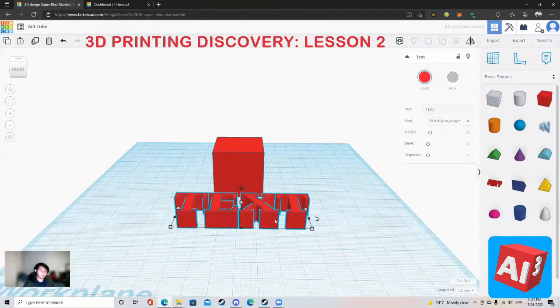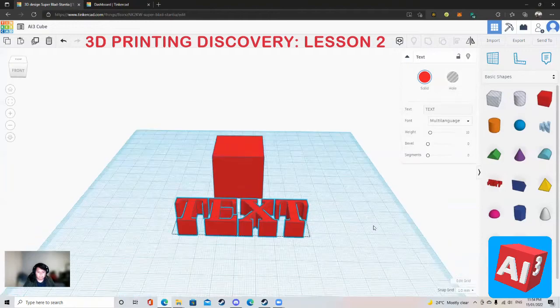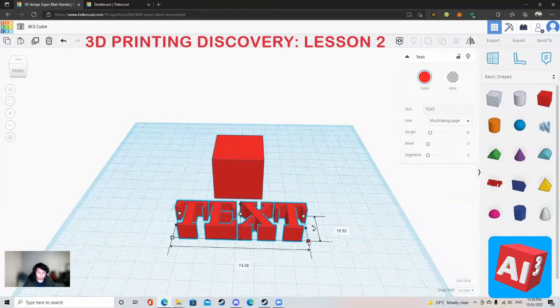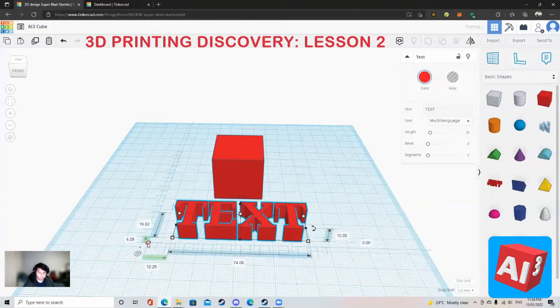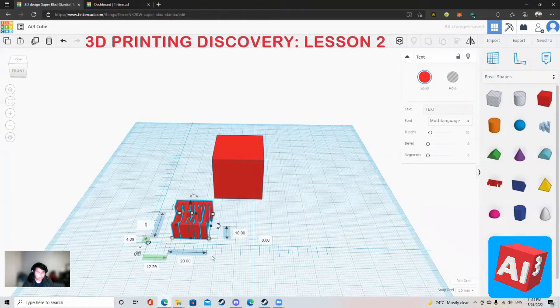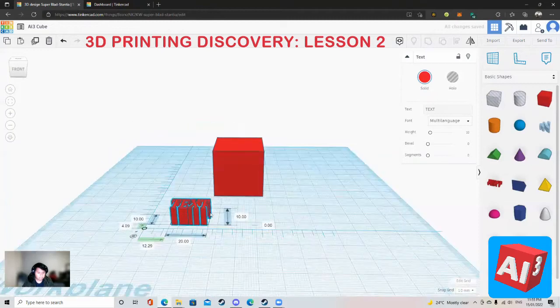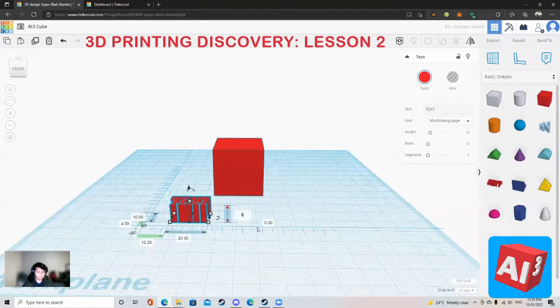Now you can see that the initial text shape size is a bit too big. To resize that, instead of just clicking this little resize tool here, I'm going to use something called a ruler. A ruler tool is very useful for resizing, guys. So just put it right there, and now we can see all the measurements of the text shape. So we're going to put this to maybe 20, this to about 10, and the thickness or height to maybe about 6.